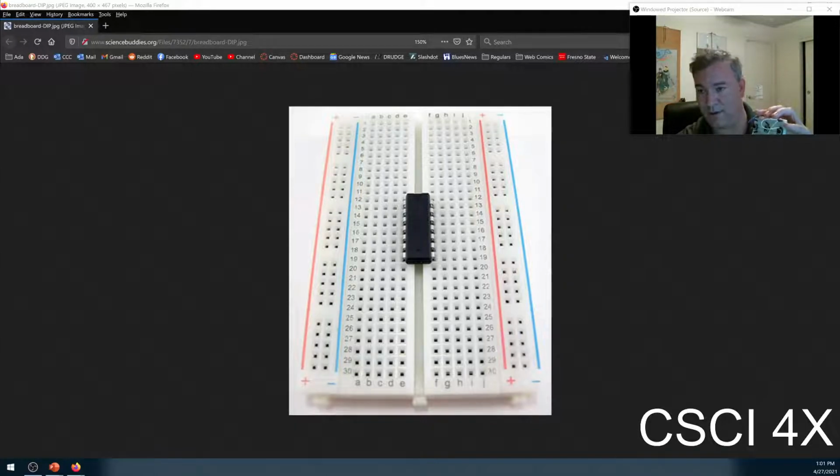You have to have a resistor or the LED will explode in a little puff of smoke. First time I taught this class, a student wired up an LED directly to 5 volts and hit the button. It popped, a little puff of smoke. He's like, oh, that didn't seem to work right. Pulls it out, puts another one in, hits the button, it explodes, pulls it out, puts another one in, it explodes. I'm like, dude, you've got 5 for the year. You've made an electric chair for LEDs, dude. Stop. You need to put a resistor on that. So that's it. It's a very simple circuit.